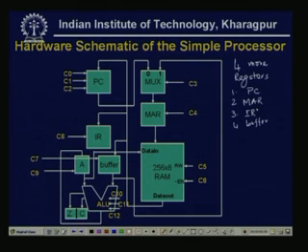The 8-bit register buffer is used to hold the data that is retrieved from the memory. So, this buffer will contain the data retrieved from the memory. Only a restricted number of data paths are available in this system, and these paths are controlled by the control inputs C0 through Cn.